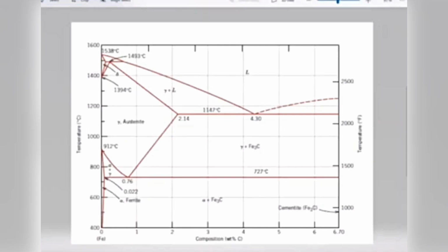Yes. In this video tutorial, we're going to be looking at the phase diagram for plain steel. In particular, we're going to be focusing in on what happens when body center cubic steel turns to face center cubic steel. Again, this is information that we can obtain from our phase diagram. Before we look at that particular transformation, let's look at a much larger phase diagram.